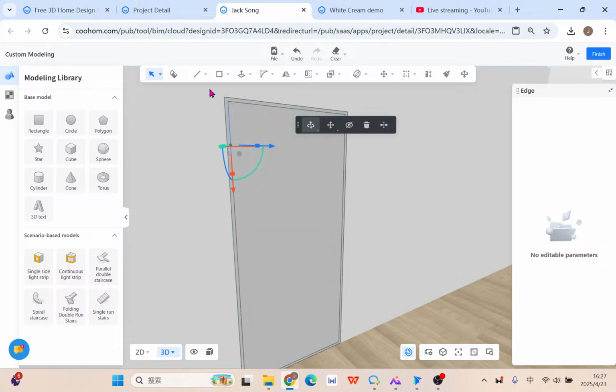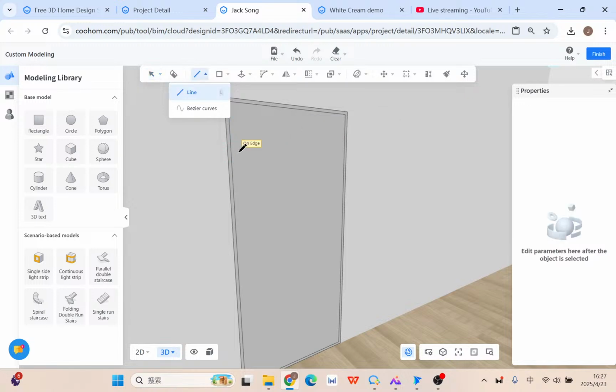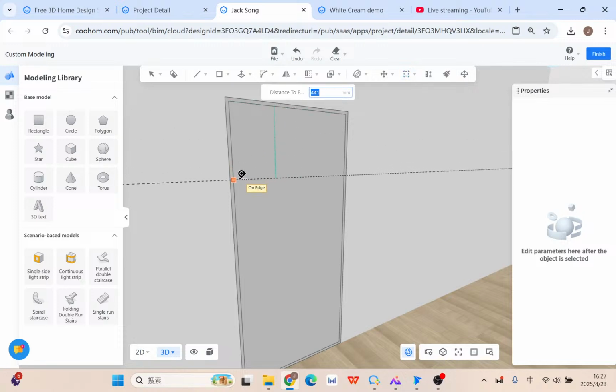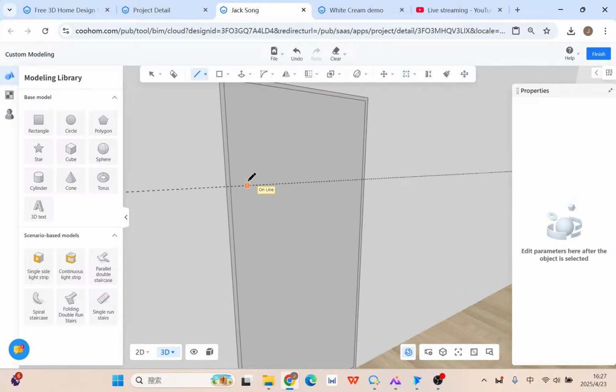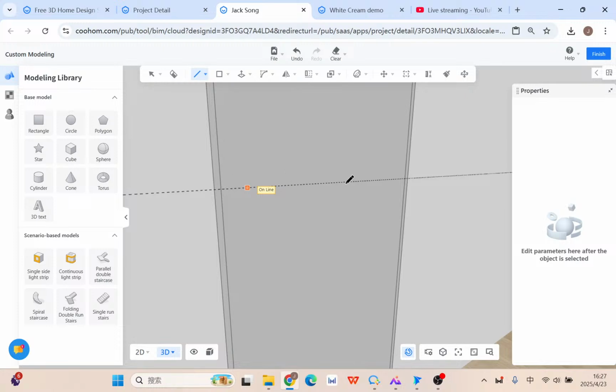And then you can also directly draw them, or for example, use a reference line as well to mark one out. Okay, see, it still auto snaps to the endpoint. And here, my suggestion is not to draw directly onto it. Why? Because I also want a distance, let's say 9, from this edge to the edge.